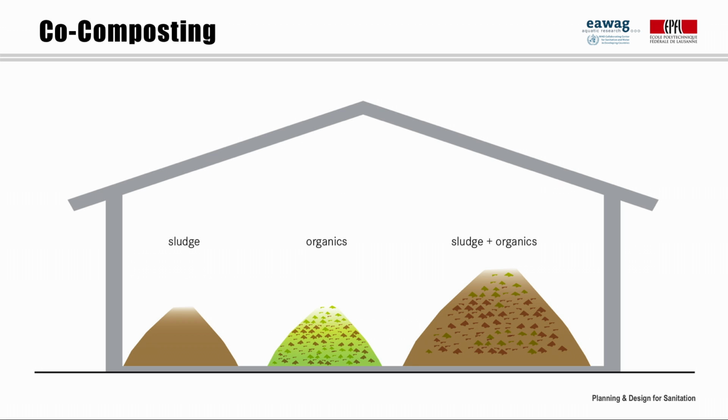Compost sounds simple, but the mixture must be carefully designed so that it has the proper carbon-nitrogen ratio, moisture, and oxygen content. Co-composting is quite labor-intensive, so it only makes sense if there is a demand for the product from customers that are willing to pay.